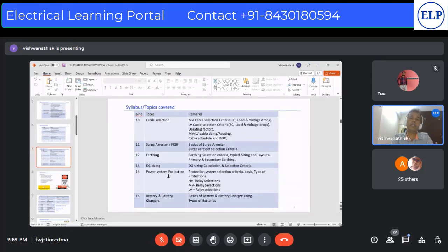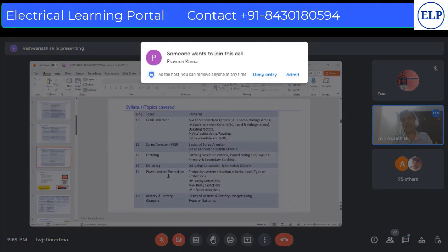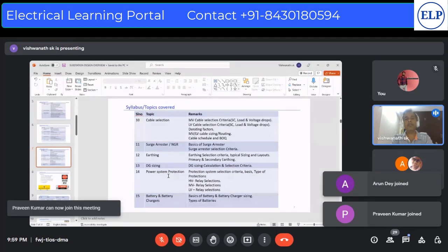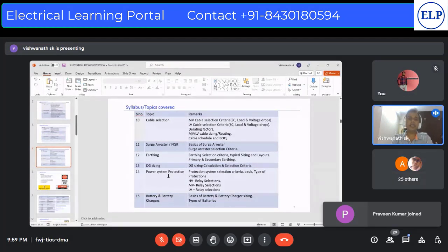And apart from that, the main protection relays, the unit protection, what we call transformer differential protection, or the distance protection, or under voltage or over voltage protection. These are the unit protections. We will make you select based on the single line diagram, which you can provide or which we can teach along the course. Once the engineer is able to read the single line diagram for protection, I can say that 20 to 25% of the work is completed.